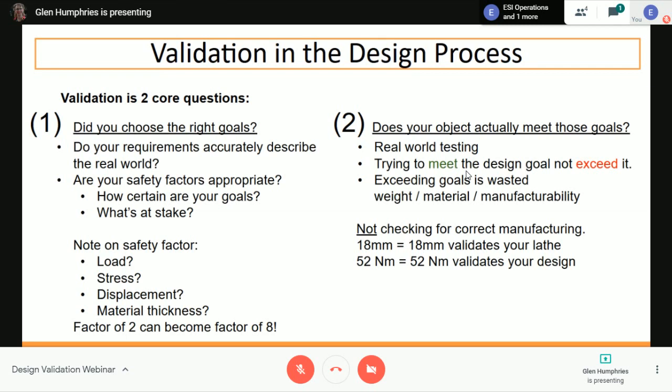There are some scenarios where, particularly in large deformation, like in springs or in suspension components, a load safety factor doesn't implicitly carry across to the equivalent stress safety factor. So sometimes the stress safety factor is more important because, say, you're very confident about the load that's going to be on it, but the stress that the material can handle is more unknown. So the steel you might be using might have a yield stress of 350 megapascals, but the quality of the supply isn't so good, so you don't trust it to that. You only trust it to 200, and there's your safety factor on stress there.